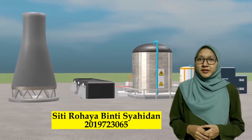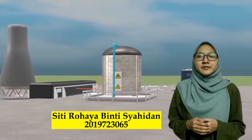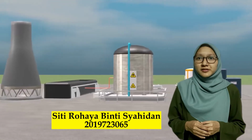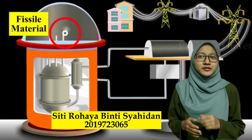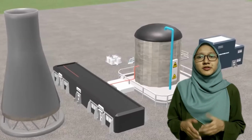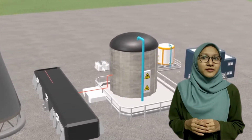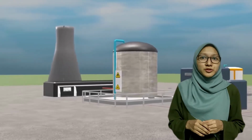Components of a nuclear reactor and their functions. A nuclear reactor basically consists of fissile material or nuclear fuel, reactor core, moderator, reflector, control rods, and coolant. For fissile material, most reactors in operation today use natural uranium as fuel. In order to use uranium as a fuel for certain types of nuclear reactor, the percentage of uranium-235 must be enriched to contain around 3% of the isotope U-235.